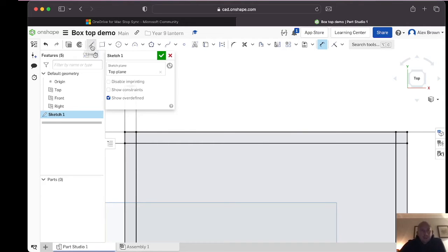Now with my line tool this time, so I'm clicking my line again up here. I need to put 4 lines on. I'll put one there, straight lines, remember perpendicular. Press escape. When you put them in, be aware, if you look at my cursor now, the little cross here, if I go to the middle, it picks up the centre. See that yellow box that just appeared? That's picked up the centre of that line. I want to avoid clicking on that.